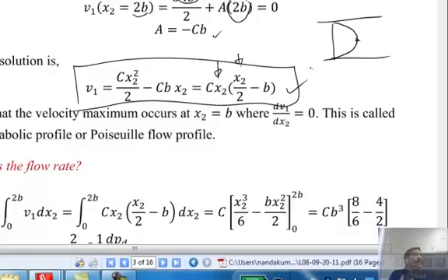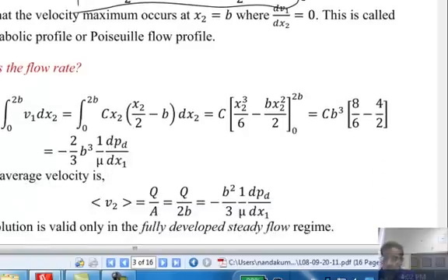And then, what is the flow rate for a given pressure drop? Because pressure drop is what you know. So you know from the pump capacity what is dP/dx that you are applying. So for that pressure drop for a given fluid, whether it is syrup or whether it is water, if you want to answer the question, how much fluid can I pump? What is the flow rate? You can answer that question also by integrating the velocity field to get the total flow rate.